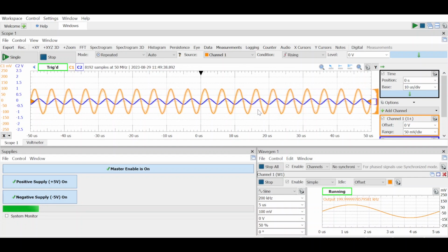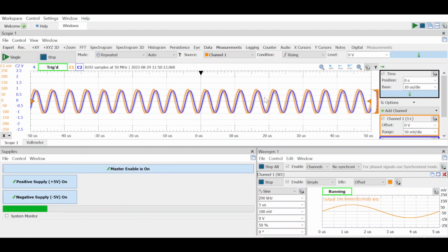As we did in the previous video, I'm now going to shift to a different op-amp. So instead of using the LM358, we're going to use the LF412, which is pin compatible. Power the circuit off. And now power it back on with the new op-amp. You can see that this op-amp is able to produce those higher frequencies with ease.